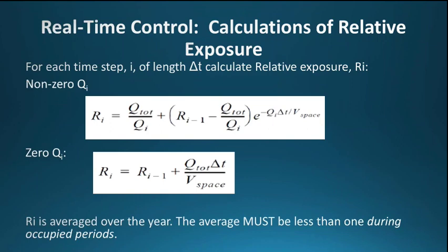When it's greater than 1, it means you have a higher exposure to contaminants, and when it's less than 1, it means you have a lower exposure. Now, ASHRAE 62.2 only says the exposure over the entire year should be the same, so you're obviously allowed times of higher exposure and lower exposure, subject to some peak exposure limits in any 1 hour. One could make different limits in different standards.